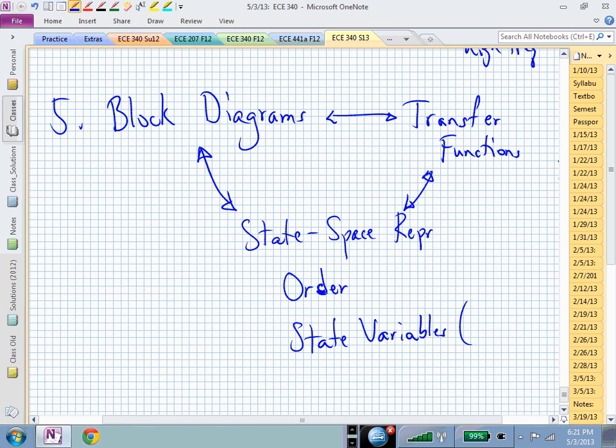And in terms of state variables in an electric circuit, how are you going to find those? So these are the L's and the C's, aren't they? Where the L's are going to be related by ELI and the capacitors are ICE in terms of their time domain behavior. V is equal to L di dt for the voltage current relationship of an inductor. I is equal to C dV dt for a capacitor.